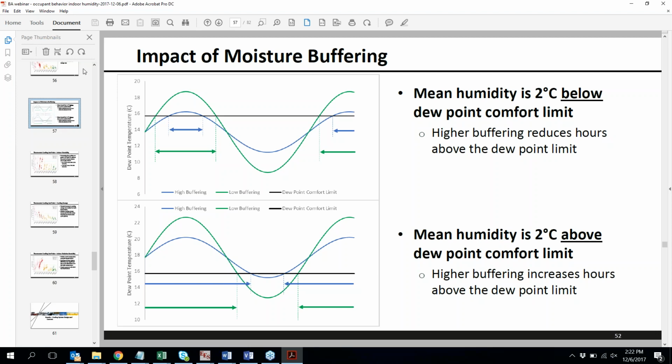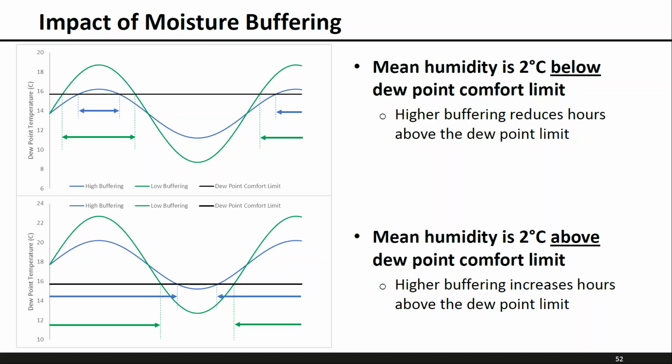So I'll throw in my 2 cents and say that it depends, which is maybe a cop-out answer, but the performance of variable speed and VRF equipment is so dependent on the manufacturer's controls of the equipment, how they control the blower airflow rate, how they adjust compressor speed.